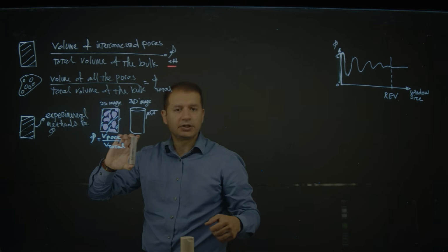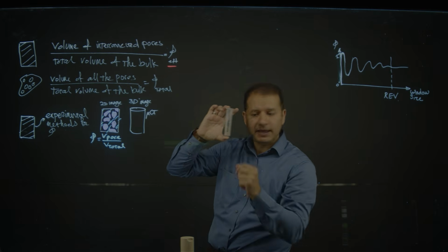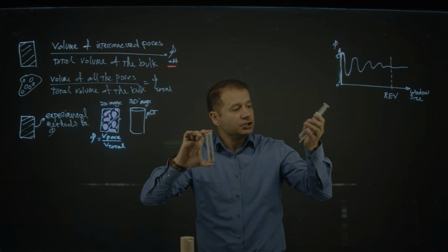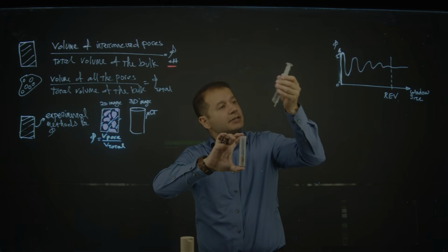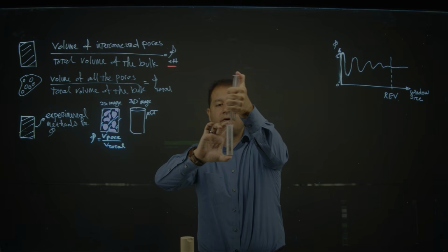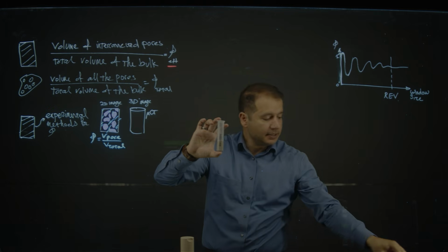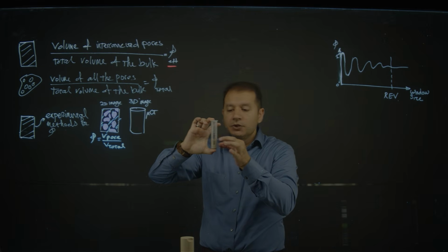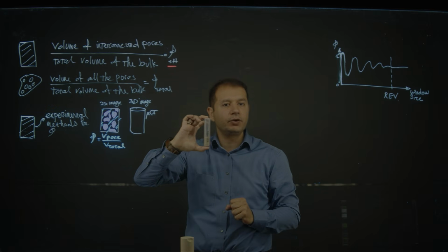So, let's do this. I want to know how much pore space this sand pack has. Imagine I have another syringe with a gauge of water, and I can add a certain amount of water that I know the quantity of. For example, 15 or 10 milliliters of water can be injected here. I'm just injecting as I'm speaking with you. And then, as I inject water here, I need to shake this sample so that air bubbles are released and water penetrates this sample fully.